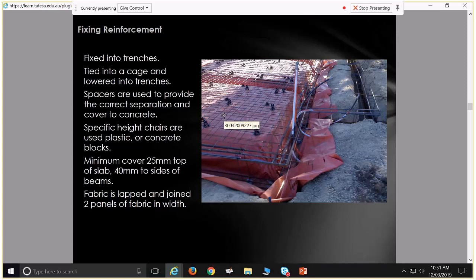So what happens is when salts are in solution, they can be carried through. They can pass through things like concrete. But then as that water dries away, those salts are left there. Those salts are polar molecules. They want to form a lattice. They want to form a shape. And so those salts will be between the grains of sand and so on in your grout or your mortar or something like that. And then they start forming their little diamond shapes and wedging things apart.